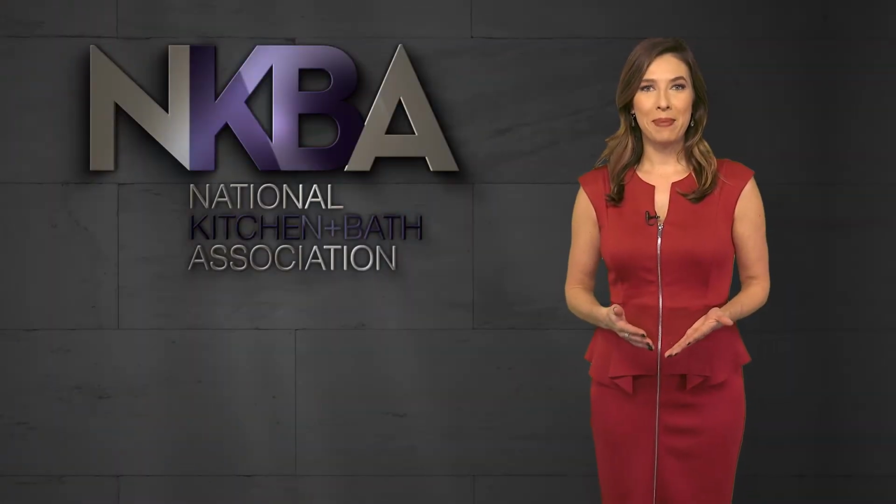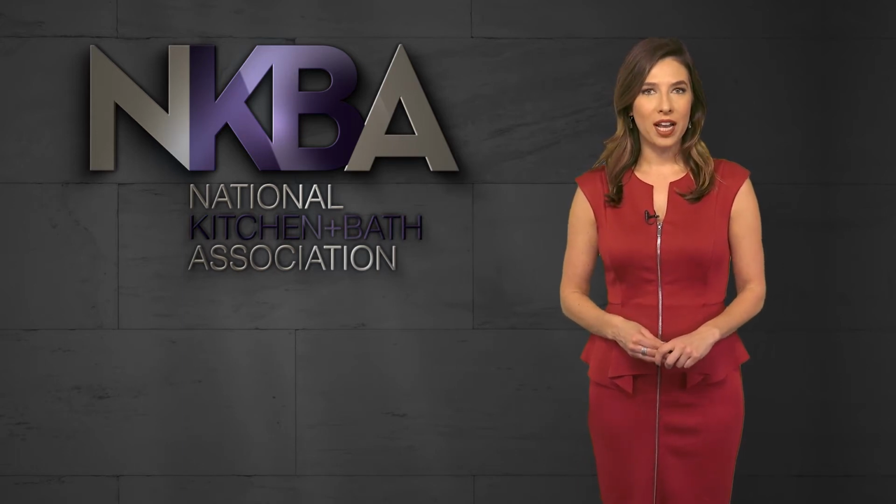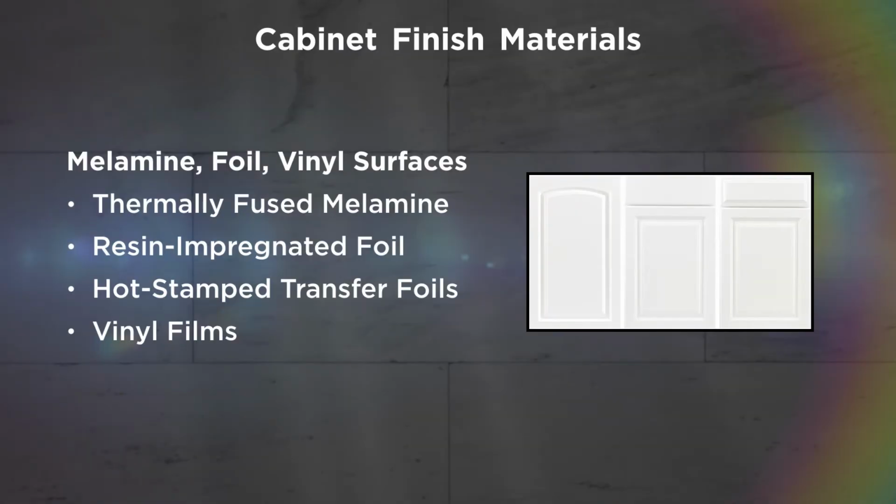Once you've selected the best core option based on your design, time to pick from one of 3 finish categories. Category 1 is melamine foil and vinyl surfaces: thermally fused melamine, resin-impregnated foil, hot stamp transferred foils, and vinyl films. These finishes are typically the thinnest as well as the least expensive.